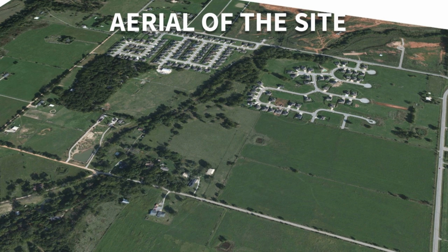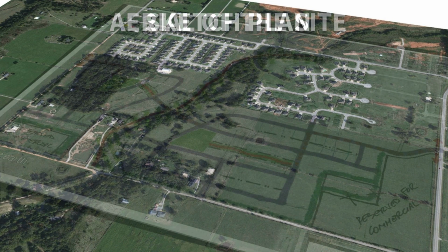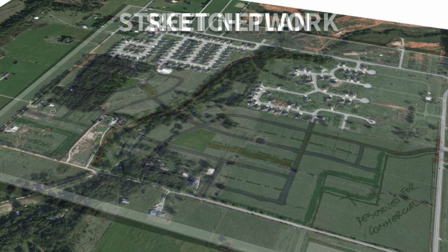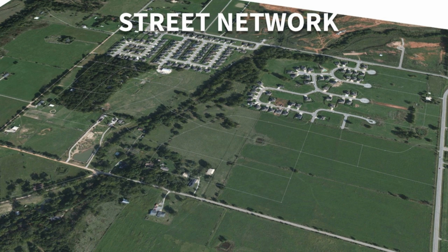Walking through this example, we had this site with some vacant land, and the plan we were developing stressed that they need to start tying their neighborhoods together as they experience outward growth. Again, starting with pen and paper, just a quick sketch plan on top of a Google Earth image. We see the street grid and some of the parcels where we wanted to preserve that green corridor. We georeference that JPEG and bring it into CityEngine, and we start to draw out our street network. Using CityEngine, we draw the street grid tracing over top of that aerial.